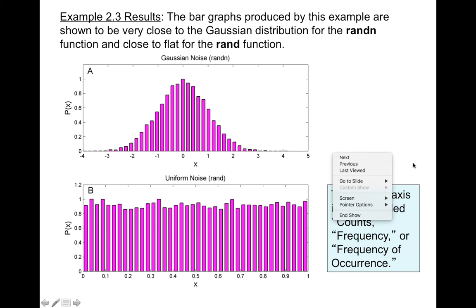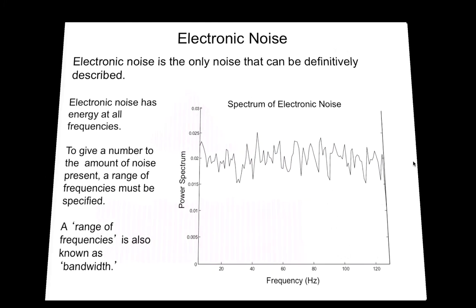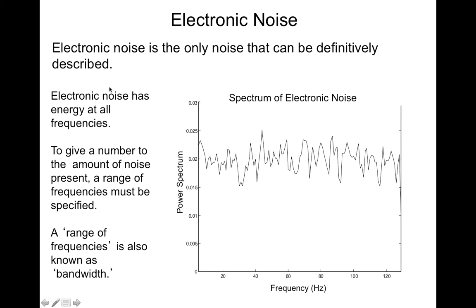There is a section in your textbook on electronic noise and the generation of electronic noise. It's a useful topic. We'll go ahead and look just really briefly. Basically, electronic noise is present any time you're making a measurement, and you have physical sensors and transducers that make the measurement. So it's specified typically over a bandwidth or range of frequency. It's characterized as being a roughly uniform distribution because it's called white noise, and that just means it has effectively a flat distribution across all frequencies.